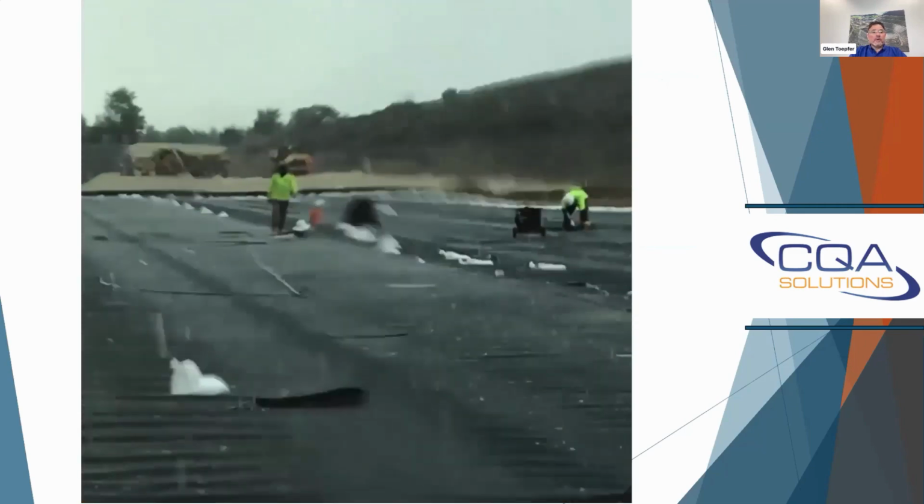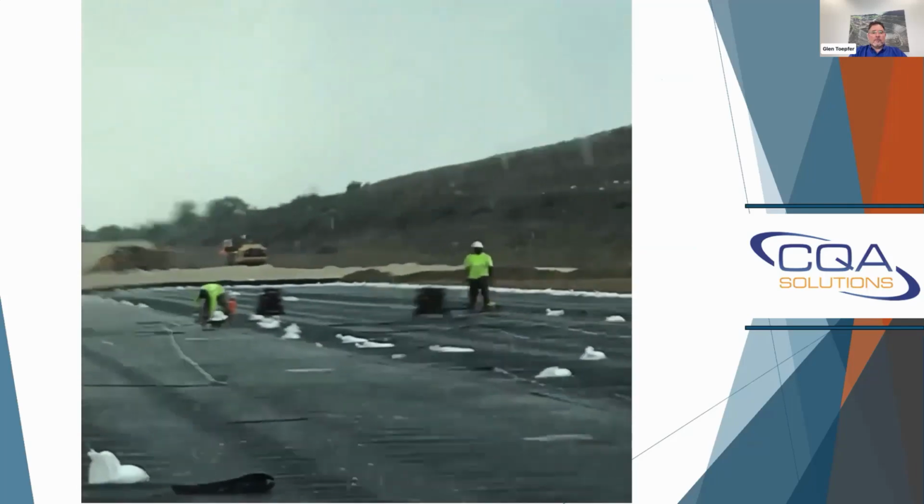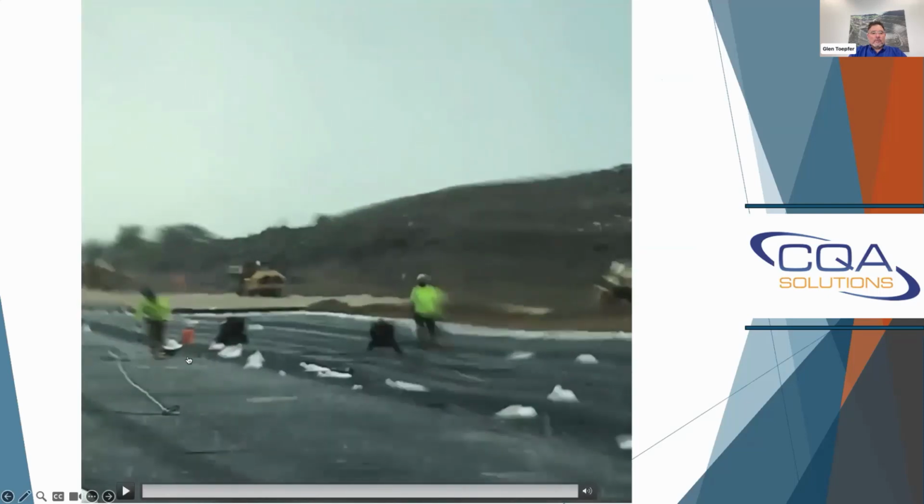Here's the weather. We have some installers out there. They got a good downpour and they got a hard hat on the fusion welder to at least keep it dry while they're welding in the downpour. But quality is even secondary at this point. This is a big safety issue, having electrical components, electrical cords running all over a conductive geomembrane, which, an HDPE geomembrane without the conductive backing is conductive, and they're welding in a downpour, something that shouldn't be done. Now that's something that's beyond the installer or the manufacturer's control, but there are actually installation guidance documents from the manufacturer that don't address weather.